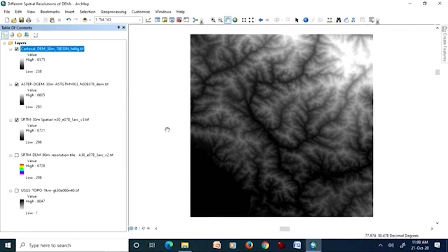The only thing is that random point generators and random selectors are available in standard GIS software. By employing those, you can definitely assess in a good way the quality of an input digital elevation model for your area. But this exercise has to be done every time you change the area.